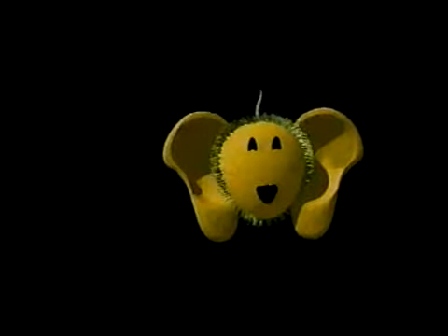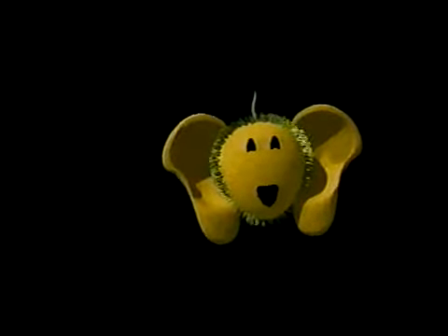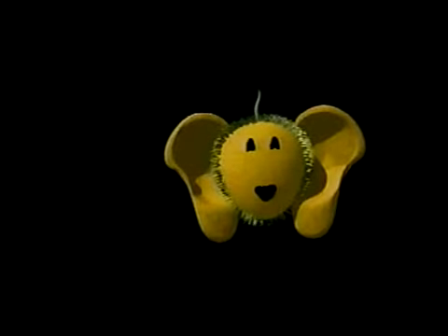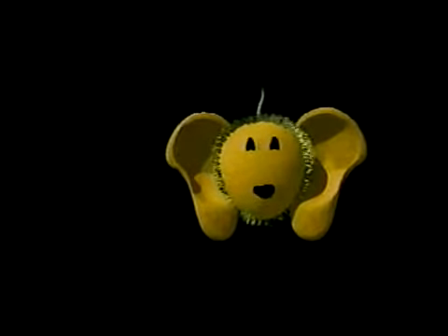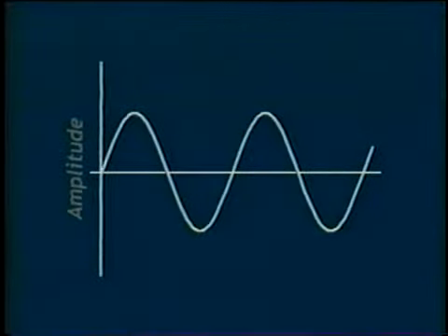A better understanding of noise involves quantifying its perception. Physical measurements of the strength of the wave are explained first, followed by perceptual measurements. We talked before about the amplitude of a wave. The amplitude of a sound wave can be quantified by measuring the associated pressure disturbance. In other words, we need to measure the change in pressure from its ambient value.